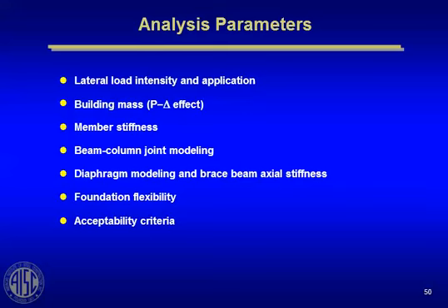Why? Because it's usually a taller story. And if you take that tall story as pinned at the base, you're going to put a lot of extra steel in those beams and columns in that first story to keep that story drift under control. So one way to mitigate that problem is to count on the actual stiffness that's there at the foundation when you do your computer model. Don't be afraid of doing that, because there's a simple way to do it that I'm going to show you here in a second.